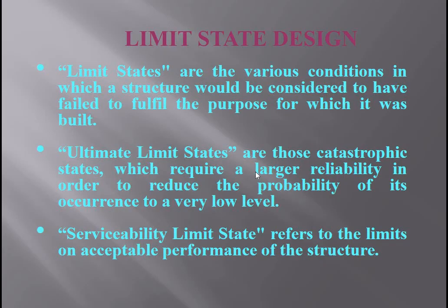Now next, so this is the reason why the working stress method has become obsolete, outdated. So now people are thinking about limit state designs. Whatever designs we are going to perform in this course of SD1 are all based on limit state designs. And for limit state design, the IS code is IS 800:2007. Okay, not 84. The 84 code is based on the working stress method. Now 2007 is completely based on limit state theory.